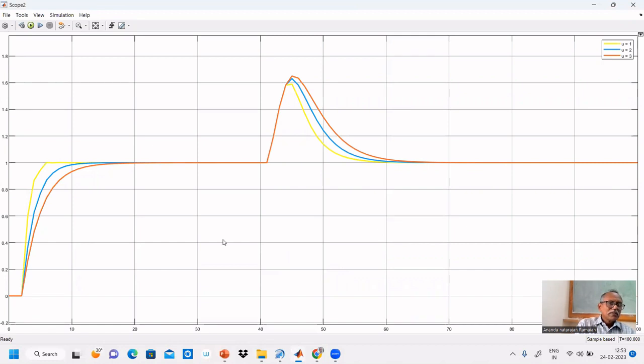Here also, it is the ideal case. That's why there is no overshoot. You notice that we designed for e power minus 1.346. What is the assumption we made? It is first order response. The assumption made is first order response. That's why no overshoot, because ideal case, no overshoot at all. The response and assumption are the same. What is the assumption made while designing the Dahlin's controller? It is a first order response with dead time. That's why the response also has the same, no overshoot at all. Because ideal case, already I told you that it is the ideal case.